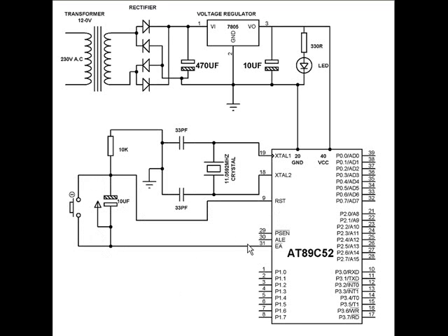And pin number 31 is to be held high. That means this is connected to positive. Pin number 31 is held high always. That is for the purpose that if we wish to program it while it is in the circuit, then this particular pin will be used. Since we are programming it externally, when we take it out, program it and bring it back, this pin, as per the manufacturer's data sheet, is required to be connected to the positive point. So pin number 31 is connected to the positive point. So these are the standard connections.